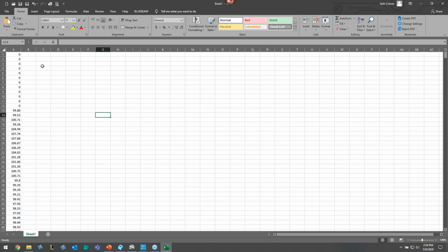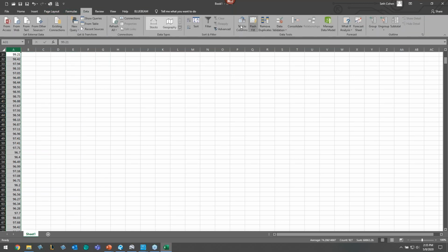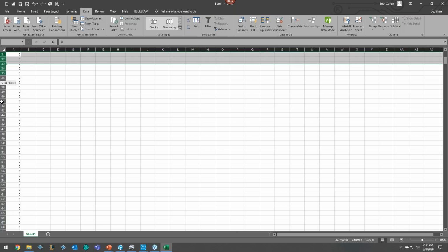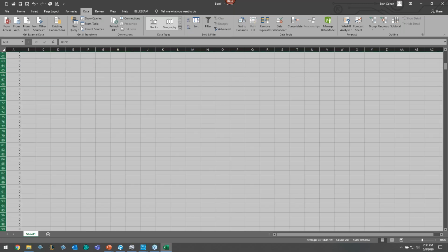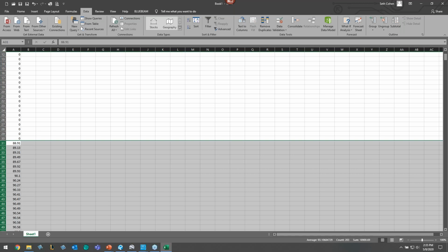Now, I am noticing that I have some 0 elevations. I don't need those because basically the floodplain wasn't in those areas, and that's okay. So this will be enough to get me an average. So what I'm going to do is I'm going to actually sort this data. I'll just go ahead and click the column here. I'll go to the data column, and I'll go ahead and click on sort, like so. And then what I'll do is I will basically delete all the 0 elevation ranges here. I could probably get the LiDAR, but I don't really care. That's good enough. Whoops, let me do that again.